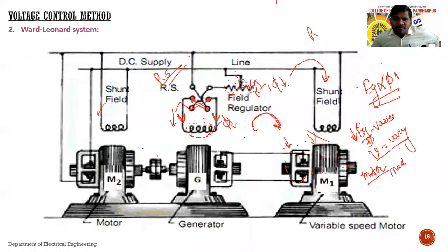If the current flowing in the field winding changes its direction, the output voltage obtained will also change its direction, as will the flux produced. If the flux changes its direction, the current produced by the generator will also change its direction. That means an opposite supply voltage will be applied to the motor. Due to that opposition, the motor will be running in the anti-clockwise direction.